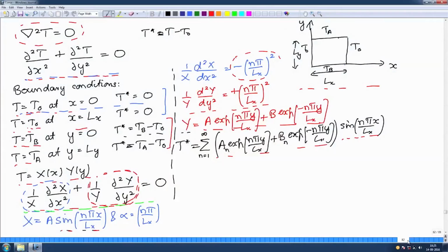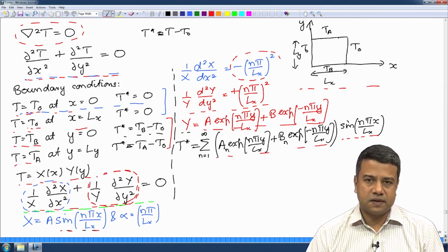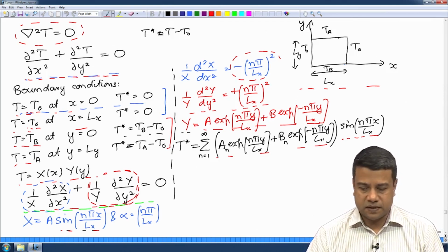And in the case of a diffusion dominated system, the equation basically reduces to the Laplacian of temperature equals 0, or the Laplacian of the concentration is equal to 0 for mass and energy conservation equations. If you recall, in the previous lecture, I had told you that in the case of equations where the Laplacian of something is equal to 0, it is called a Laplace equation, or if you have an inhomogeneous term, it is called a Poisson equation. In both of those cases, you can solve the equations using separation of variables.